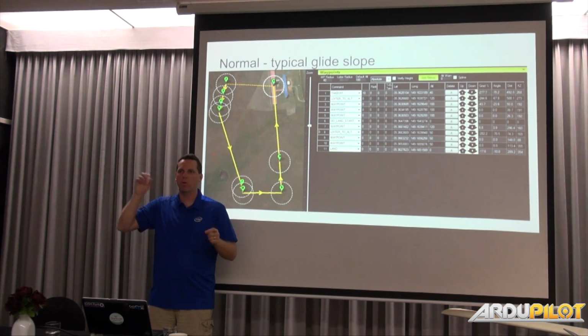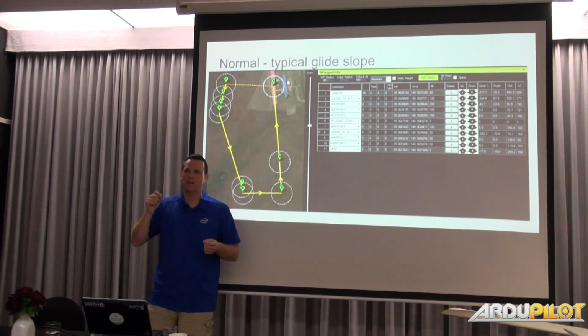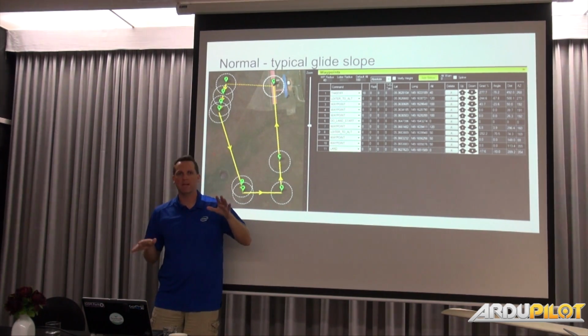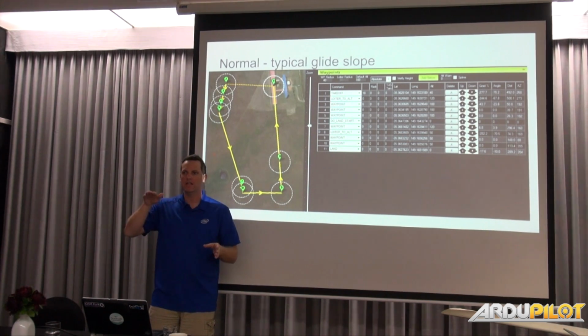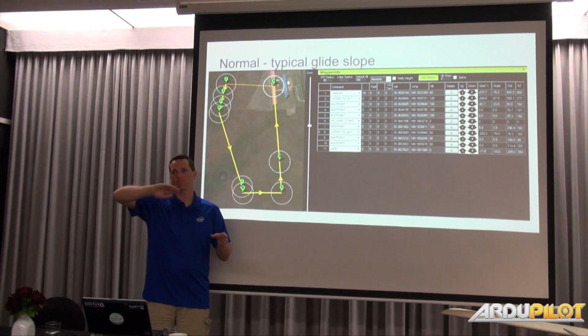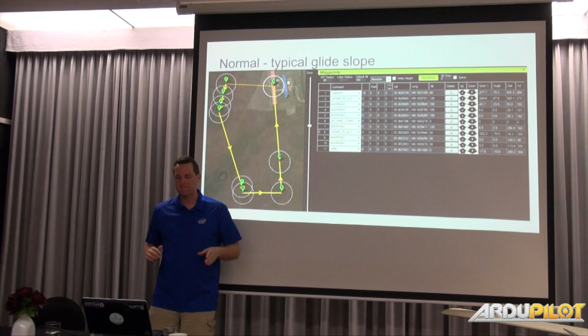Now, it won't actually do the landing unless you're actually lined up. So if you're hitting that top waypoint, which is point 10 in this case, once you've reached 10, if you're 90 degrees to it, you're not going to start landing yet. Because landing, part of it is to restrict some of the bank angles and that kind of thing, more steady. So you're actually going to start turning real slow, so it's going to be hard to line up.